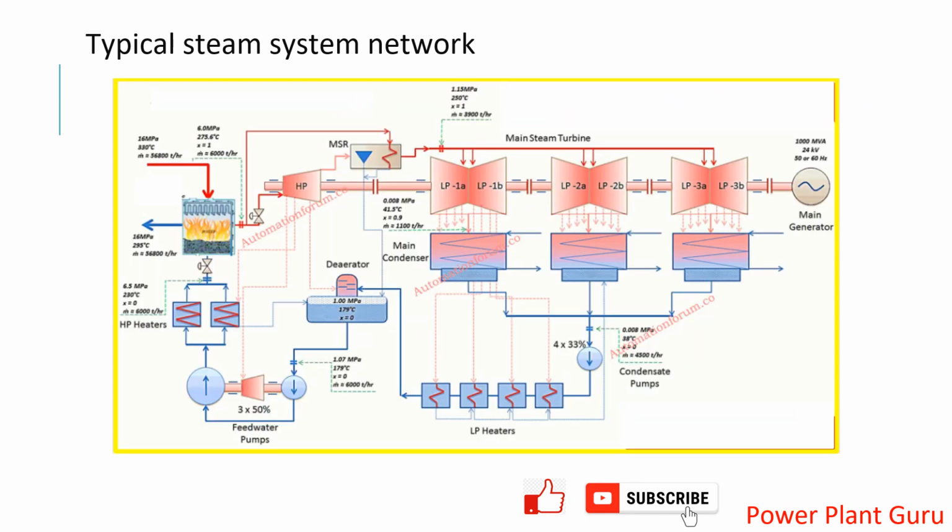So you have a different type of typical steam network, where you have your boiler, and from the boiler, the main steam line. The main steam system supply goes to your turbine system. And then your turbine HP, MP, and LP stages may have different types of letdown. So letdown or extraction steam may be a controlled extraction or maybe an uncontrolled extraction.